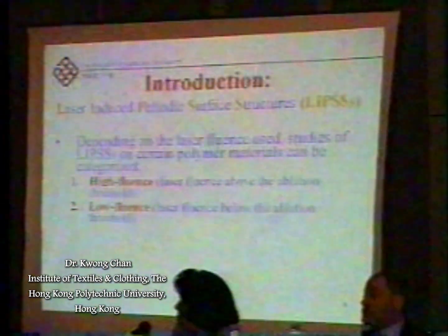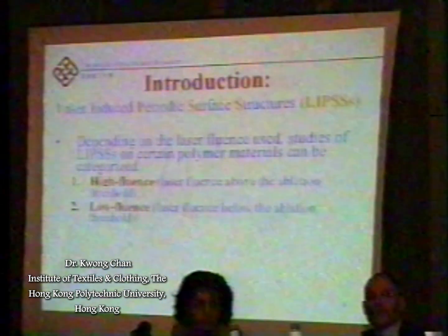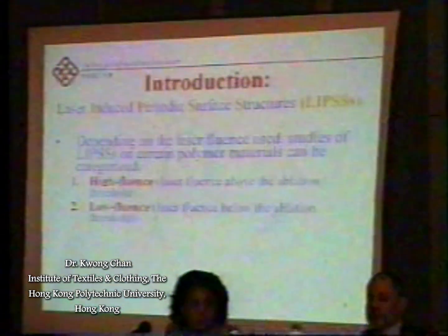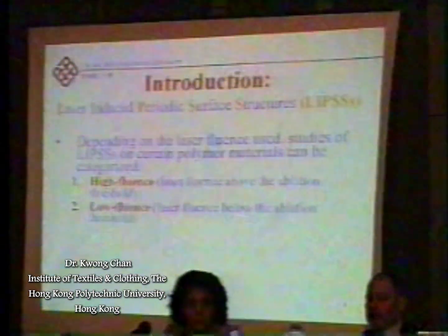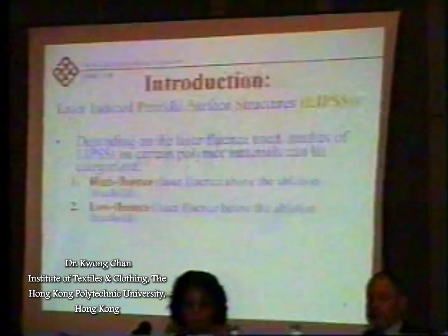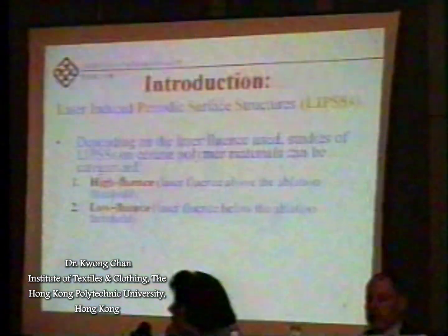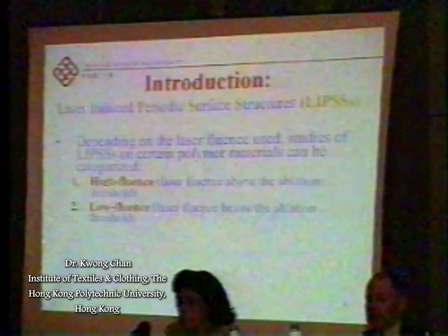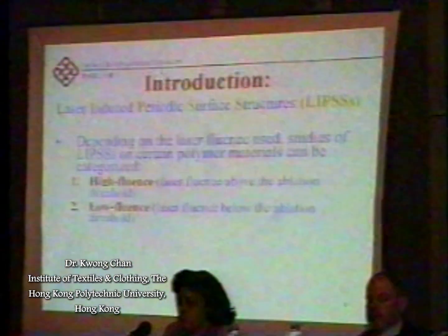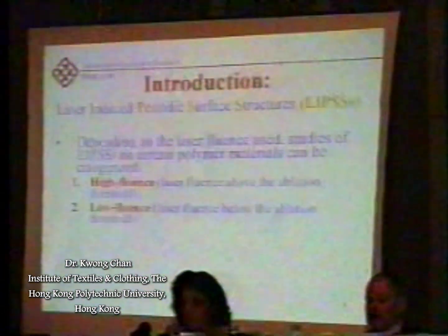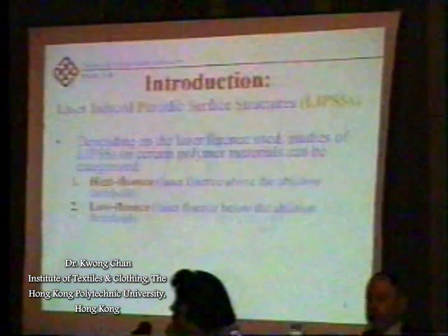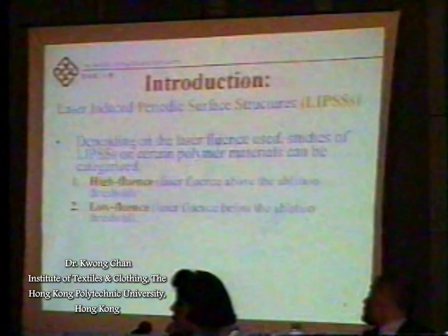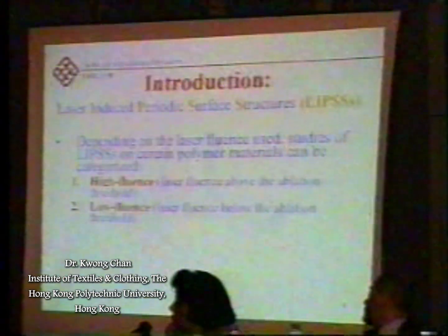So the laser-induced periodic surface structure, simplified as LIPSS, has been widely studied recently. Depending on the laser fluence used, the study of LIPSS on certain polymer materials can be categorized into high fluence, that is, laser fluence above the ablation threshold, and low fluence, that is, laser fluence below the ablation threshold.